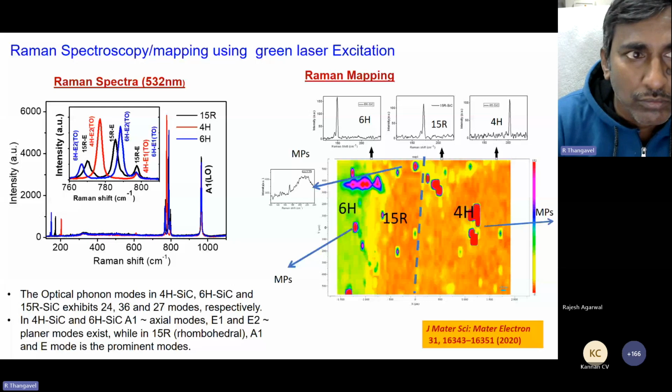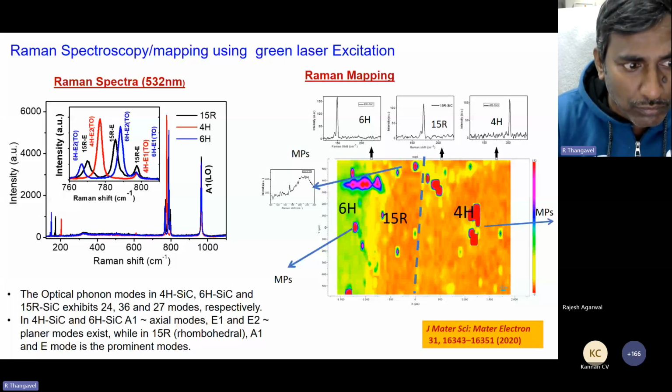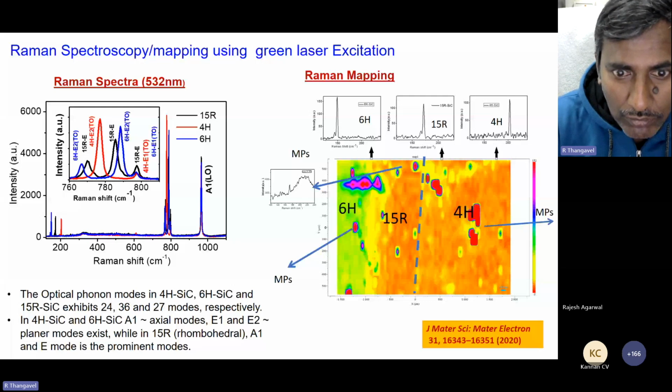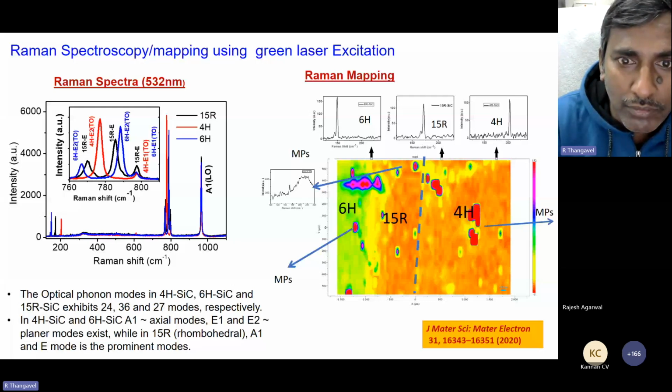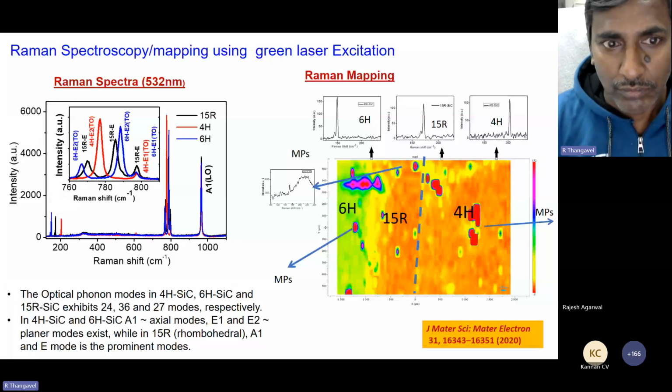Now, in the designing, what happens? The device can be designed: circuit design, stability design rules, circuit elementary design, interconnect routing, device simulation, pattern preparation, mask preparation. For photo mask designing, a photo mask is a template used in semiconductor production, especially in photolithography. It consists of transparent material, for example glass, with opaque parts or a special structure on its surface.